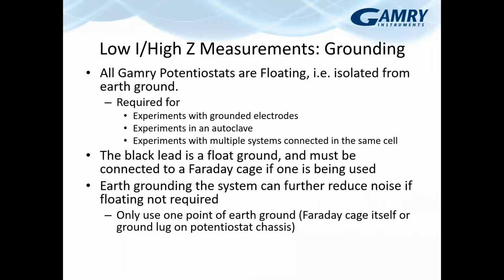Another issue is grounding. All of our potentiostats are floating. That means that they are isolated from earth ground. This is a requirement if you have experiments with grounded electrodes, if you're running electrochemistry inside of an autoclave, or if you have multiple electrodes and systems connected into the same cell. This can be like a bipotentiostat experiment where you've got two working electrodes, one reference, one counter. It might also be different actual systems.